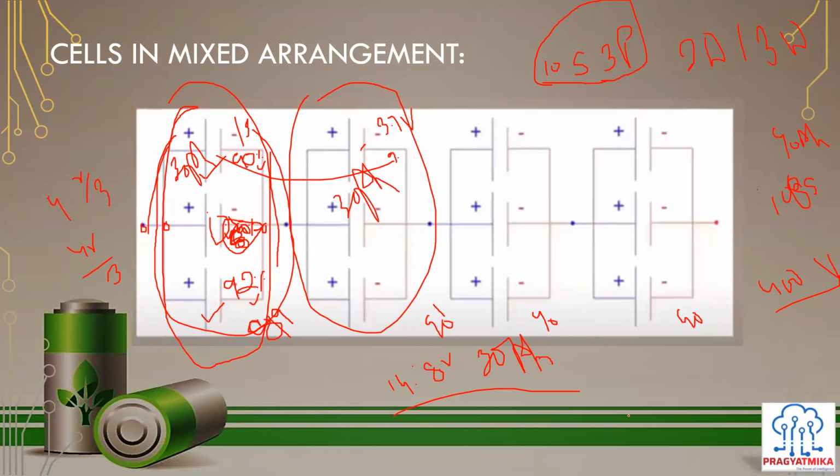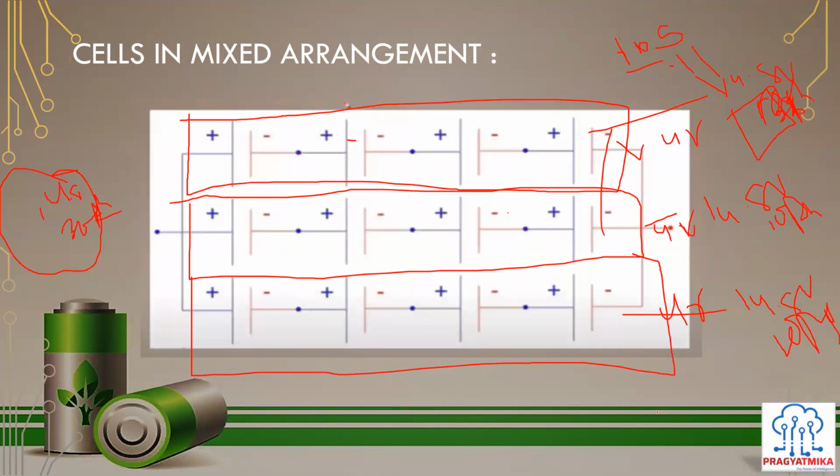So that's also one of the reasons that the standard BMS you purchase, available from China and elsewhere, doesn't have communication features, because they are not able to tell much about the battery pack. Once the master slave BMS comes into the picture, they are able to tell you, because with their help we are able to monitor each and every cell. They tell you the status of each cell, and they have communications and IoT, everything integrated with it. So that's why the design difference is there.